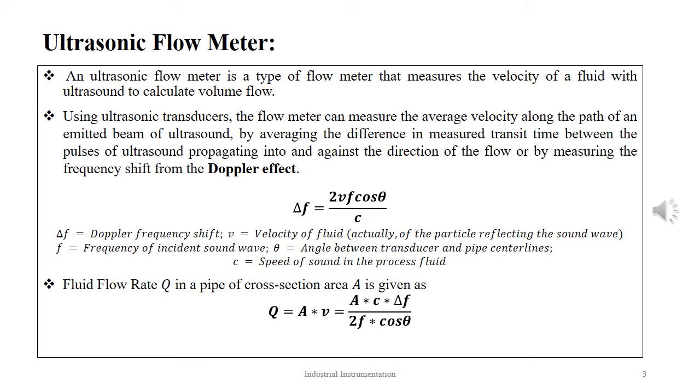Ultrasonic flow meters are affected by the acoustic properties of the fluid and can be impacted by temperature, density, viscosity, and suspended particulates depending on the exact flow meter.